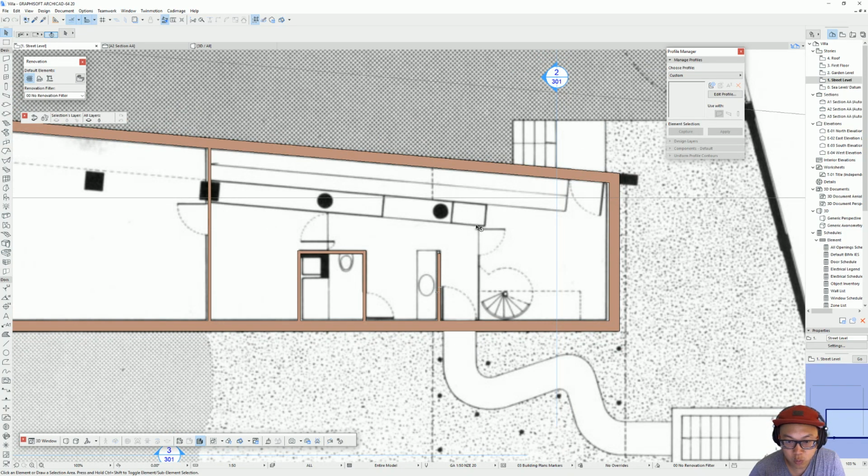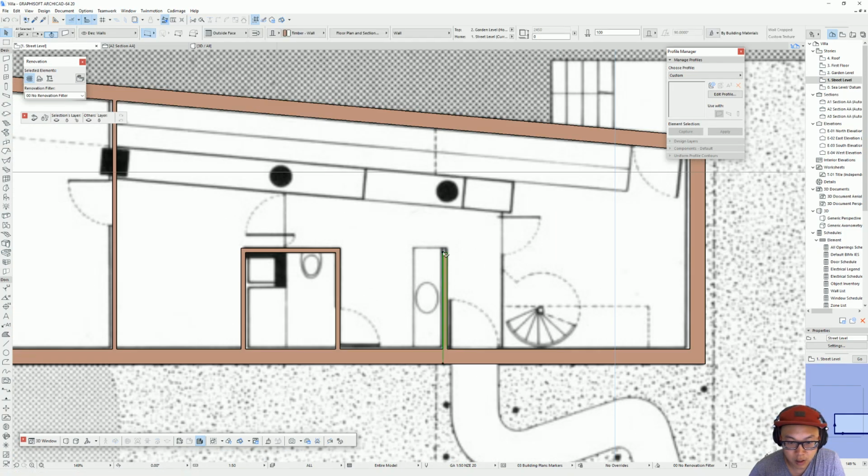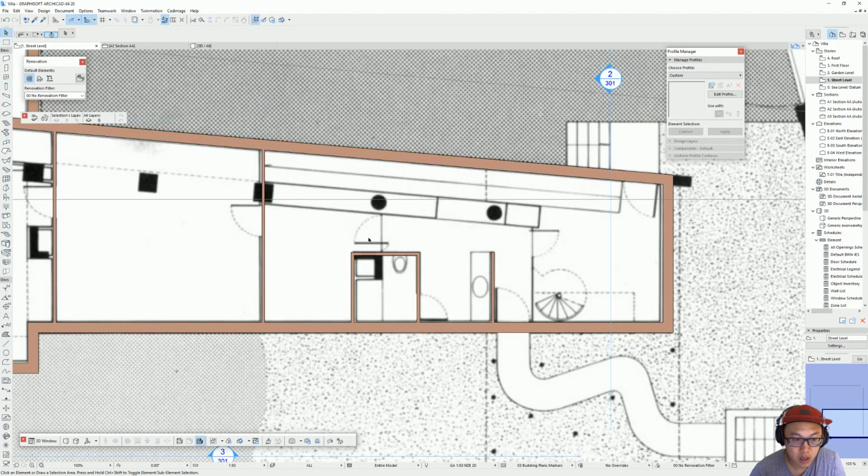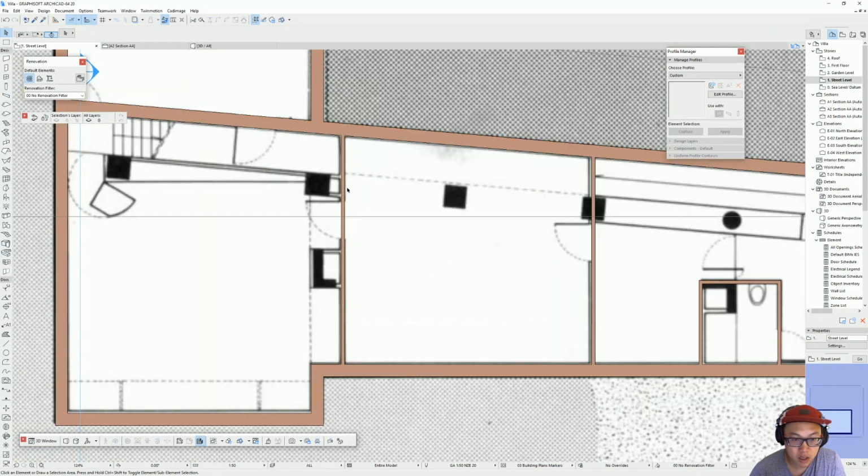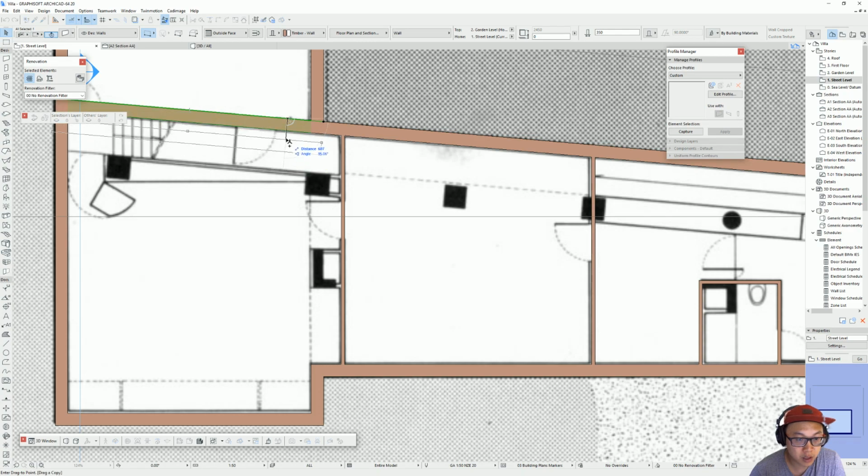And I think those are walls as well, but a bit thinner. Here I'm just gonna drag it so it's in line with this. And there's this diagonal as well. So I'm just gonna take that wall, make a copy, and try to follow that guideline, which is at 90 degrees. And 1.450. I'm gonna drag it to there. And I'm gonna resize it to 100.